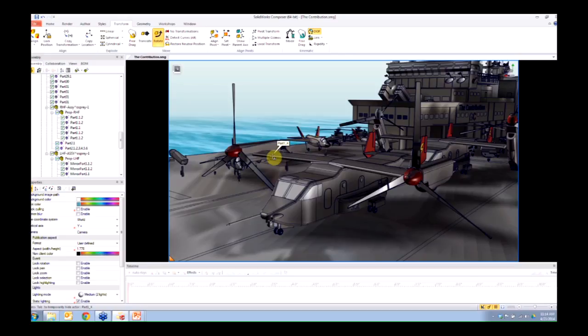Now if that didn't work, for whatever reason, there's a couple of reasons why that wouldn't work, and that's if the assembly structure between the two weren't identical. So I wouldn't really know how to do it if they're not identical, if they're not mirrors of each other. In this case they are, so you would simply zoom in, Tab that wing gone, Alt select that edge, and then tell it to rotate negative 60 degrees, and you would have the same outcome. Okay.